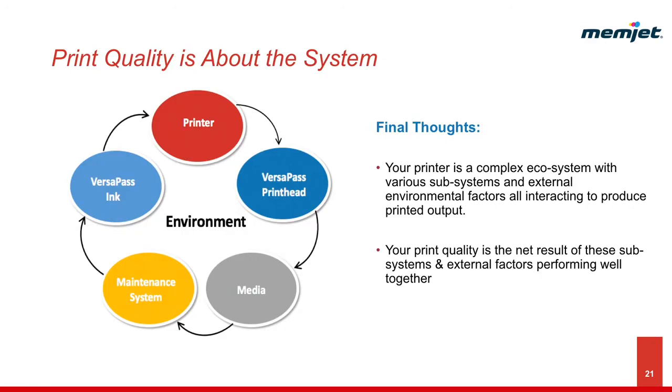One final printhead troubleshooting tip. It's a pretty normal response to assume the printhead is the culprit and change it out, but that's a fairly expensive fix. So the next time you have a print quality issue that you can't quickly resolve, try a less expensive approach. Take the printhead to a second unit.